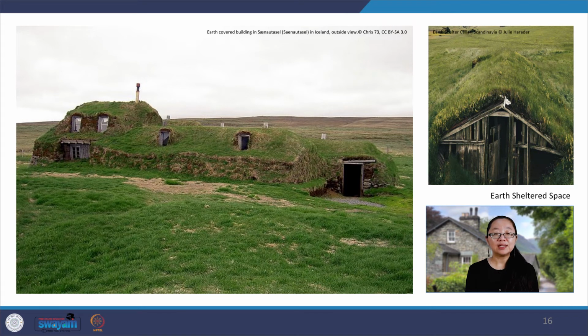For thousands of years in arid climate, earth has been traditionally used to cover roofs. It acts as a thermal mass regulating the inside temperature. Earth naturally absorbs heat and retains it before gradually releasing it into its surrounding. And due to the high density of Earth, each change in temperature occurs slowly in what is known as thermal lag, resulting in a fairly constant temperature compared to the fluctuation experienced in the outside.